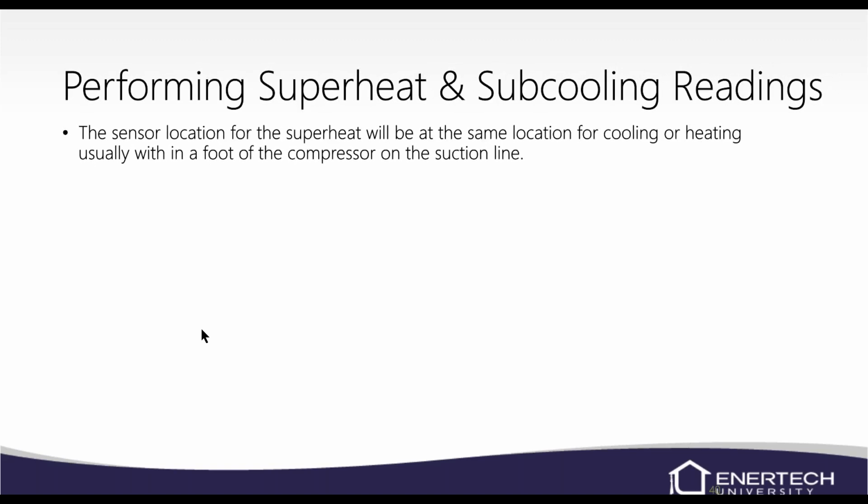Sensor location for superheat will be the same for cooling or heating, and it's usually about a foot or so off the compressor suction line. Really, you can look for the insulation that has the bulge from the bulb from the TXV, and you can check it right there. You got to figure that TXV is trying to maintain superheat, so wherever it's reading at is where you need to be as well.